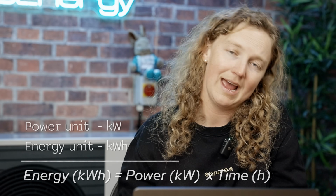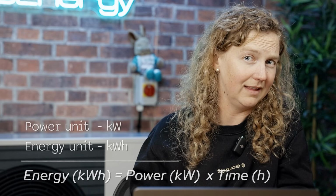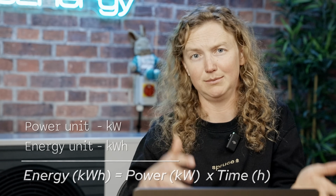Those things have different units. So power has units of kilowatts. That's how quick it's moving. Energy has units of kilowatt hours. And that's because energy is power times time. So if I'm losing heat at 5 kilowatts for an hour, then I've lost 5 kilowatt hours of heat.